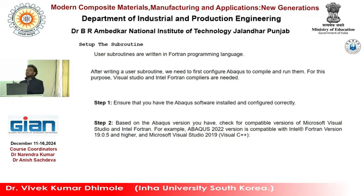So in the documentation it is referred. If you have this Abaqus, you can go with this Intel Fortran compiler and this Visual Studio compiler, right? Then you can install those things on your computer, give them permission, give them the environmental path. What is the environmental path? You can see here, edit environmental variable, the environmental editor, right?